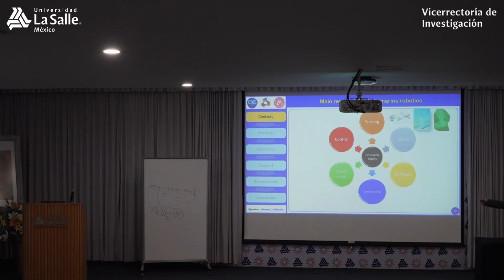One of the topics, the first one, concerns the perception of the environment, the sensing of the environment. Perception, pay attention, it's not so easy. If you have a mobile robot on the ground, it's very easy to use satellite, GPS, Wi-Fi, radio, all the signals, they work. However, underwater, nothing is working. This is a big problem. And also, the conditions of work underwater may be very difficult. Sometimes, look at this picture. The visibility is so bad. So if you use a classical camera, it does not work.